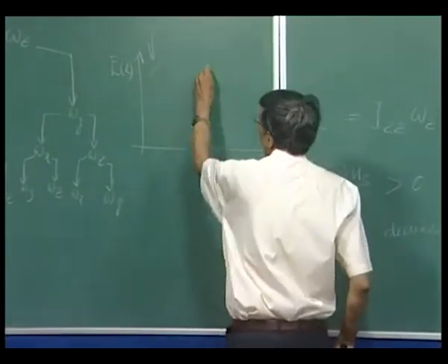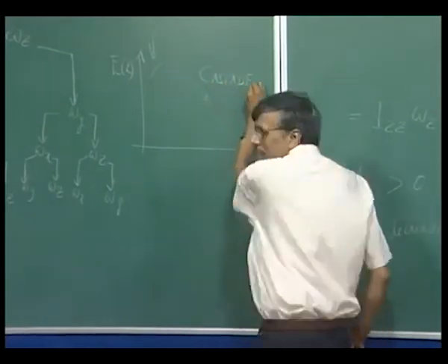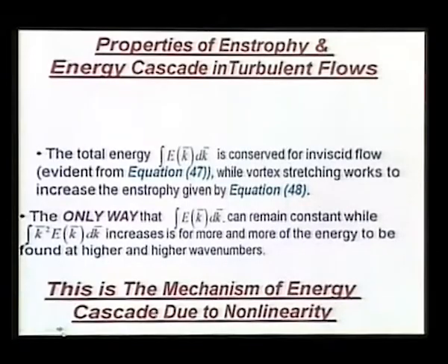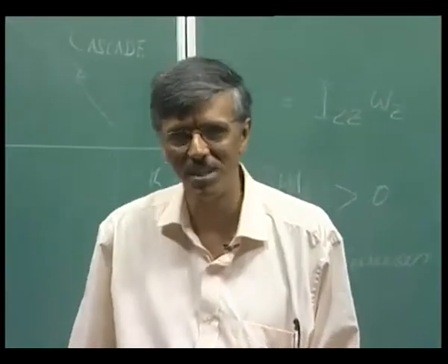So, this is what we would be calling the cascading effect. The energy cascades, that is what we are talking about. So, that is why I show it with a very bold remark here, that this is the mechanism of energy cascade, and this is a nonlinear effect, right. In fact, this idea has been so entrenched into the thinking of the turbulence community that people do not like to acknowledge that there can be any other mechanism of energy transfer.